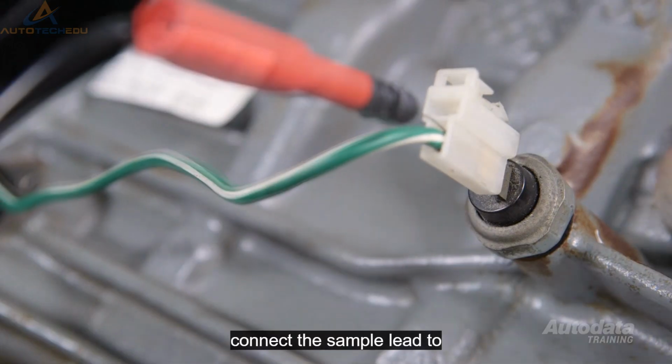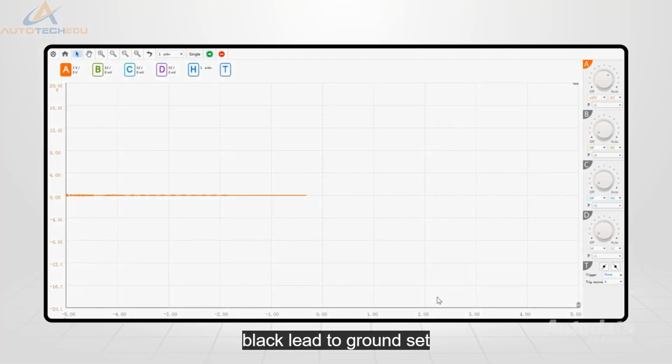Connect the sample lead to the signal circuit and the black lead to ground. Set the Y-axis to 20 volts and the X to 1 second. This vehicle has a single wire oil pressure sensor, so we should see the voltage trace start at 0 volts with the ignition on, then shoot upwards of 12 volts with the vehicle running.